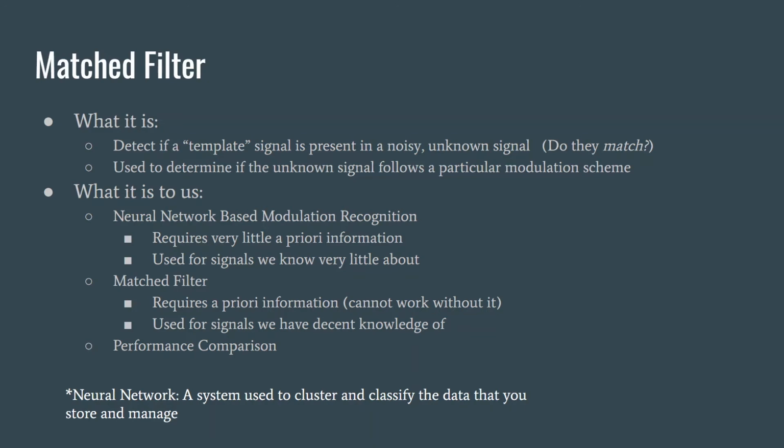So for the technical parts, what it really is, it's a process to detect whether a particular piece of known signal exists in an unknown and noisy signal we received, and check if the output of the filter is the same as our template signal. It can also show us if the unknown signals we received match the modulation scheme provided locally.